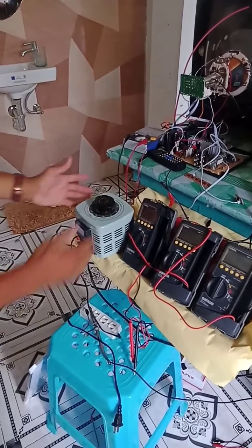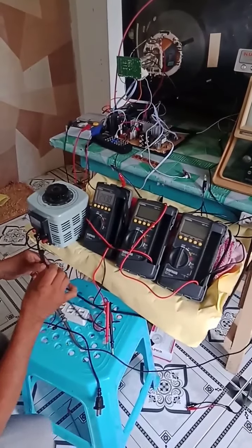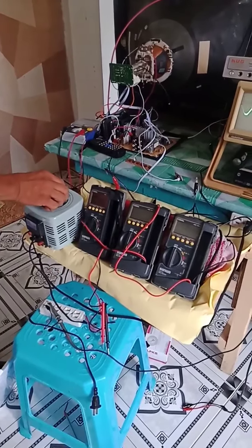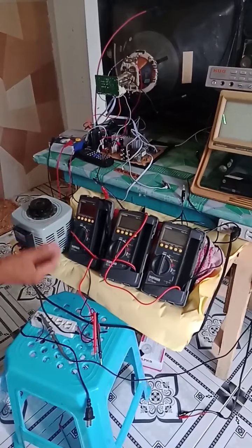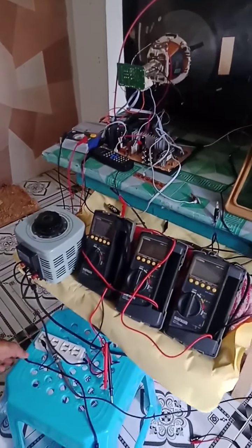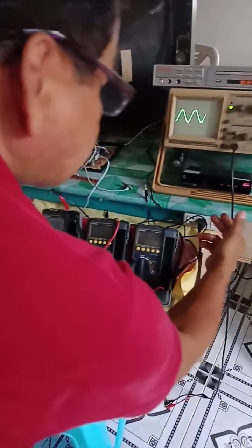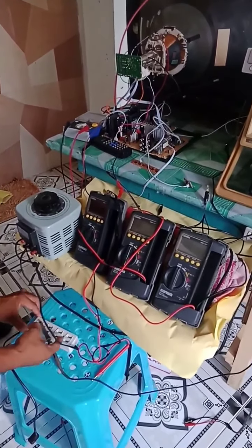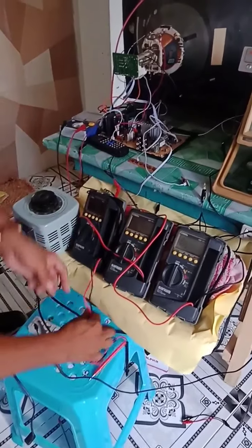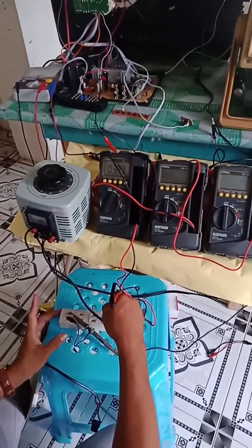Okay. Variac transformer actually has two windings. The primary, we have here, and the secondary winding as the output line. It is equipped with a variable, or the so-called rotor shaft, that will vary the setting of the voltages at the output. Now, actually, the primary winding is connected to the outlet that distributes 220 volts to this variac transformer, and the output now is at this outlet. So let us measure the output voltage of this secondary winding.